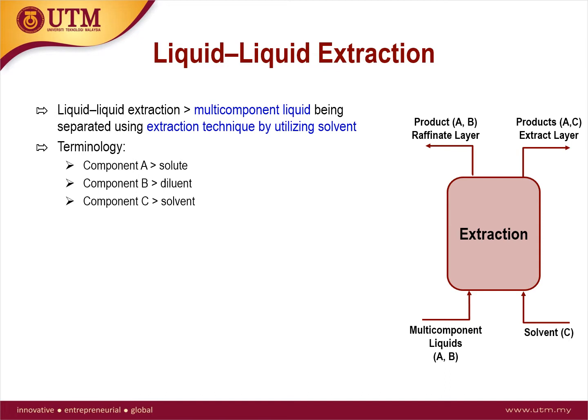However, the feed solution that is depleted in the solute is called the raffinate layer. Alright, and you can see from this liquid-liquid extraction, the raffinate layer consists of the products A and B, where the percentage of A is reduced as compared to the feed stream.